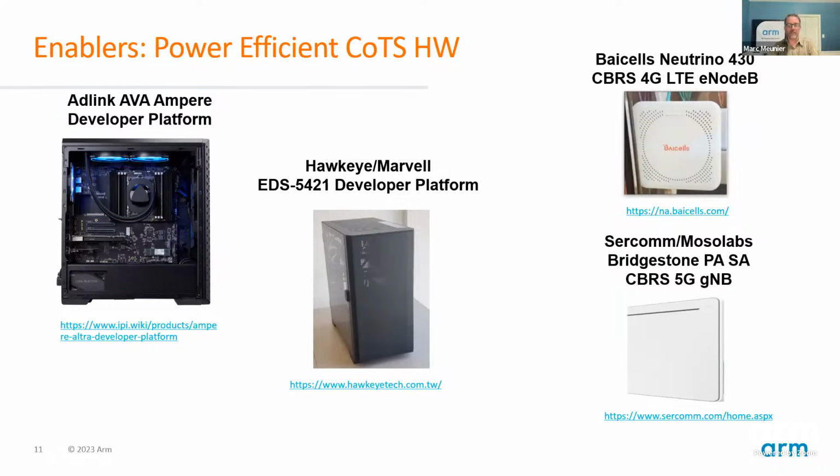Of course, Jim mentioned this early on. We wanted to be able to plug this into a general power outlet. That includes a generator. So if you're out in the wilderness and you need to run this system, a standard 1500 watt generator with a 15 amp output at 110 volts will run any one of these servers, with all the equipment that we've described here. So that makes it very portable.